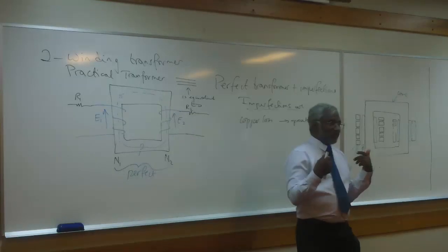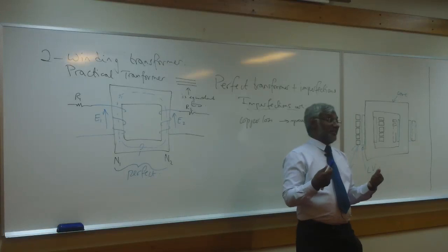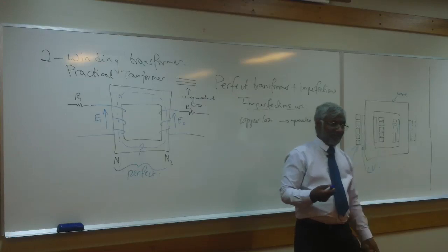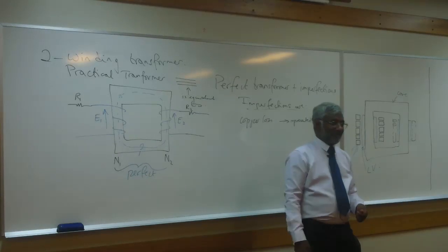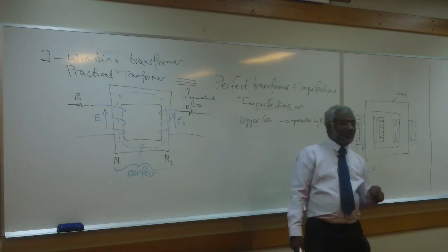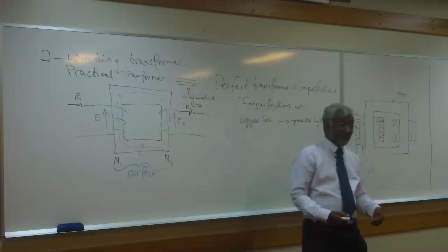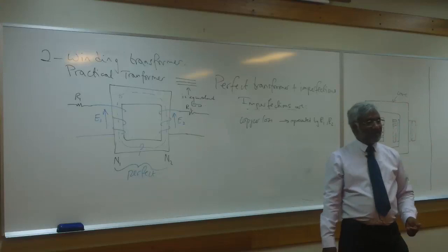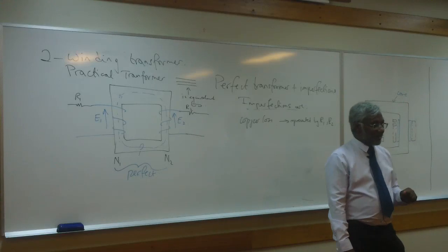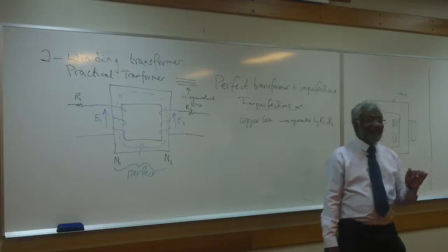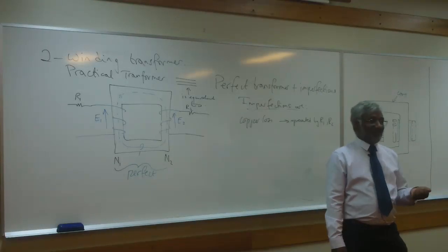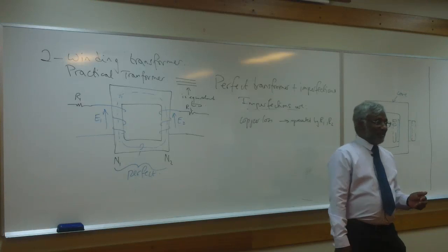Like, I am not a resistor, but I have resistance. So I have a resistance. What would be my resistance from head to foot? Well, everybody is different. It depends on your skin, and on your physiological condition. Like if you're sweating and you're not wearing anything, from head to toe might be some number. But as engineers, especially as power engineers, it's good to have some feel of what it can be, especially in the worst case scenario.